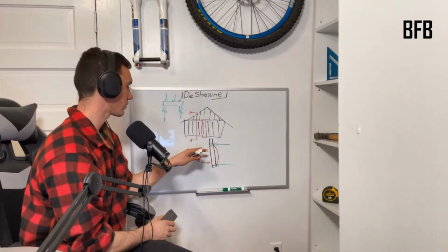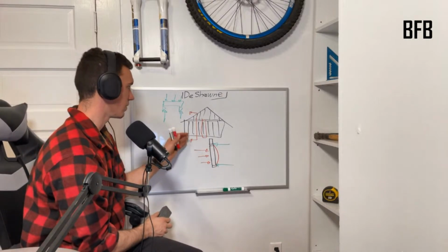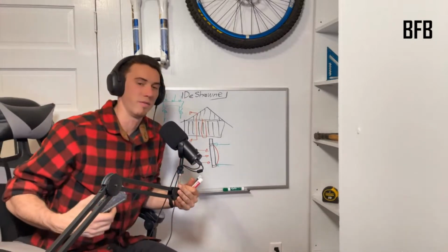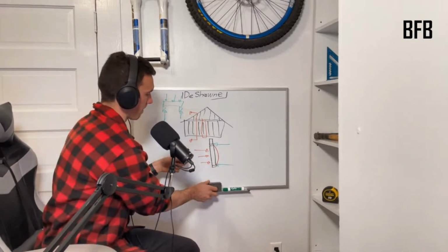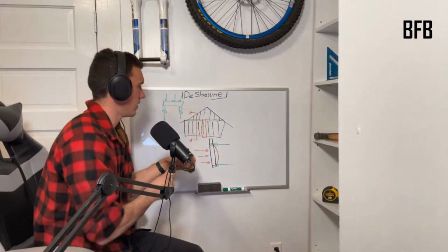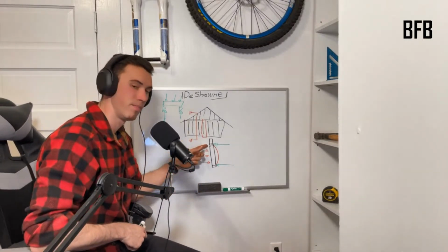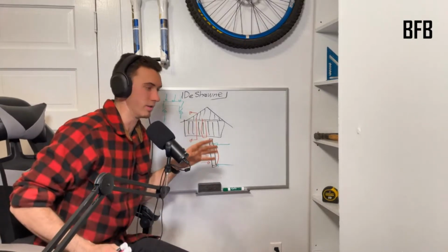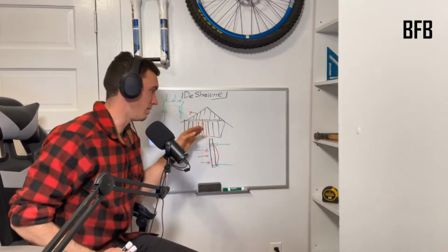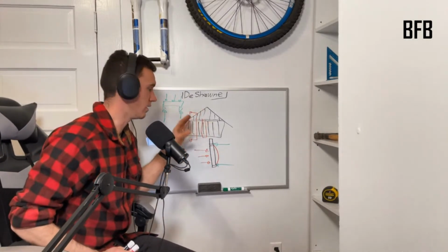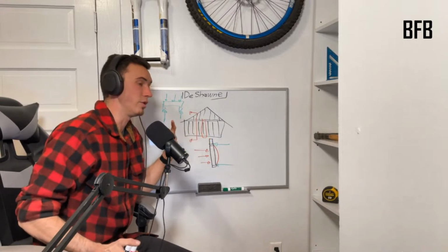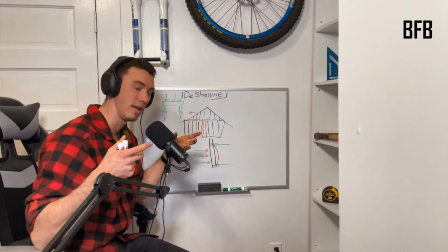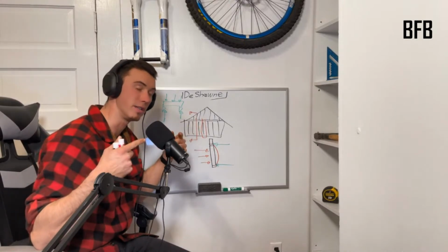So, where was I going with this? Oh, right. So stick framing. So the reason we have this whole ceiling diaphragm thing going on is we handle this problem with system design. And I know, really exciting words. So system design basically means that the house is designed, the way we build houses here in America, at least, when we do stick framing, we have decreased the structural member size and increased the quantity and decreased the spacing.